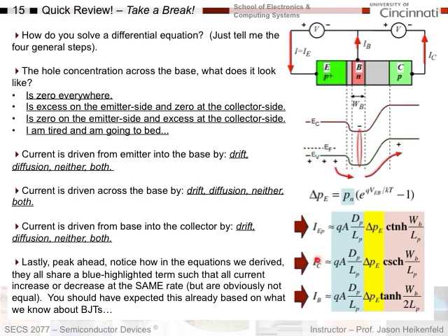Furthermore, remember that the base current and collector current were proportional. You amplify base current into collector current with a proportional amplification factor. So just a constant you multiply times base current gives you collector current. So if base current goes up, collector current goes up at the same rate. And so these equations, and I'll make more sense of them in the next part of this lecture, will start to make a lot of sense, because you'll see that you can break them down into things that are just telling you how the currents in a BJT work.